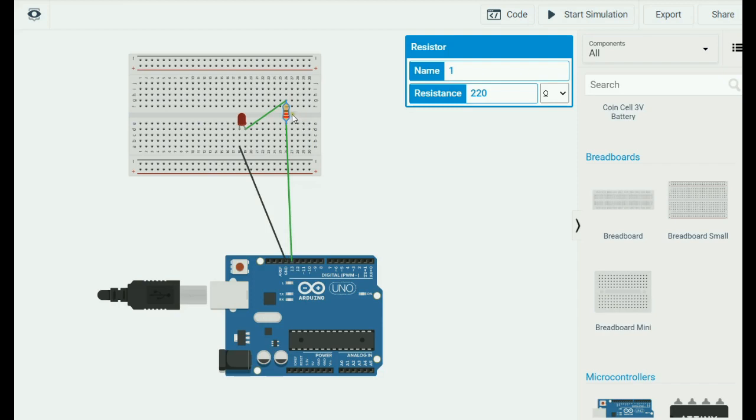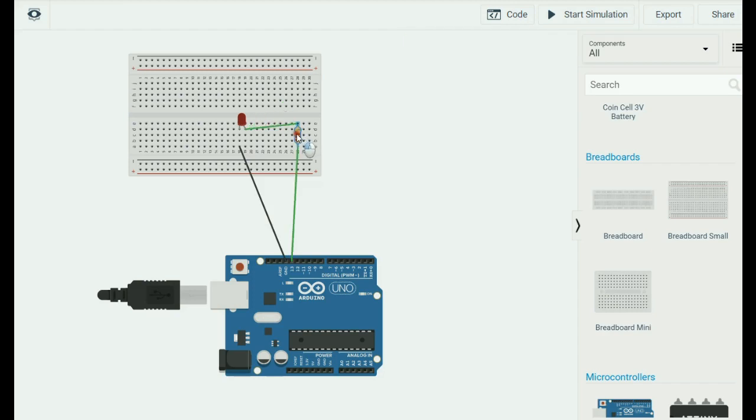Now, one other thing you need to notice is I put the resistor over here like this. I did not go and place it like this. It would be no point connecting it like this, because all of the holes behind here, they're shorted together. So this end and this end would be shorted together. So whether you have a resistor there or not, it would not matter.